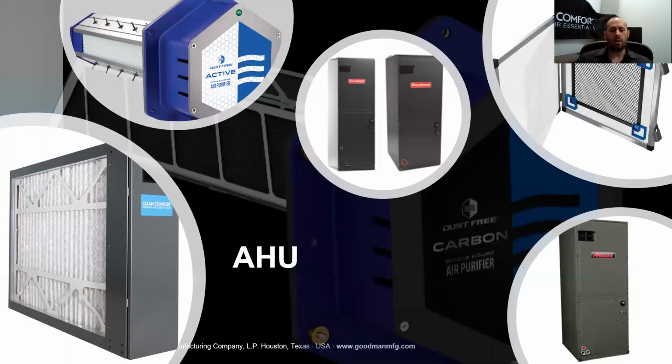Let's look at some commercial equipment. Small CFM air handlers are common, even more so now with the popularity of VRV. There are a lot of options with this type of equipment. You can use a media air cleaner. You can use an electronic air cleaner. You can use a hybrid air cleaner. You can use UV lights. You can use purifiers, either carbon or oxidation. You've got a ton of options when you're dealing with a standard small CFM air handler.